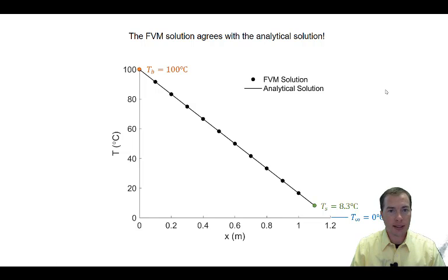Hopefully you have seen in this lesson that the governing finite volume method equations form a set of coupled linear algebraic equations. These equations are most easily solved using matrix methods and can be done in the MATLAB environment or any other computer environment that you are aware of for solving coupled sets of linear algebraic equations. In this video, I demonstrated how to solve a coupled set of linear algebraic equations using the matrix inversion method in the MATLAB environment. In the next lesson, we will look at a two-dimensional case.